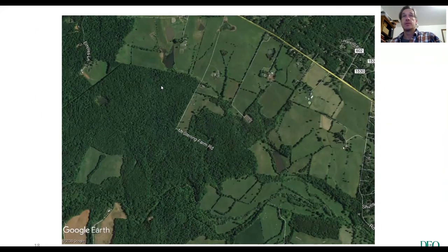Aerial imagery, very important, not expensive. It's usually one of the first things people go to when they're trying to figure out a groundwater system. And recently, check this out, they've come out with LiDAR imagery, which is measured elevation data that's collected by bouncing a laser off the surface of the earth and getting the refractions from the laser to get really precise elevation measurements of the surface of the earth.